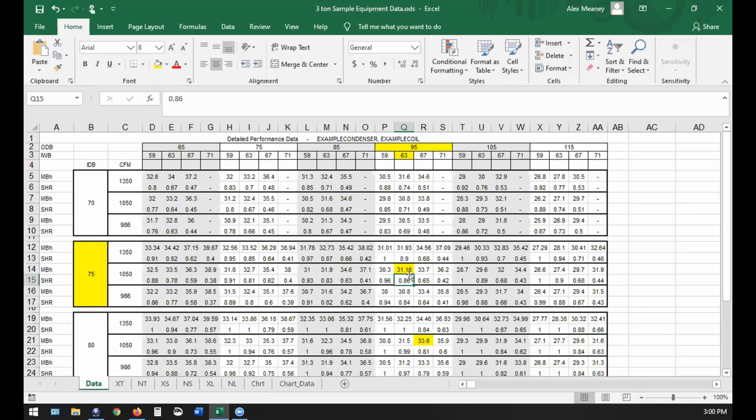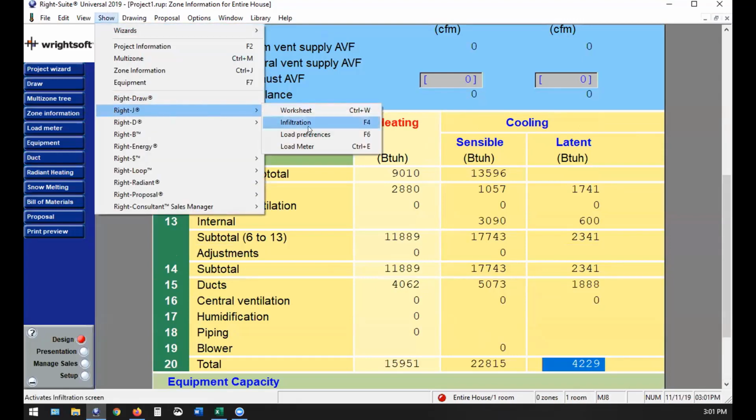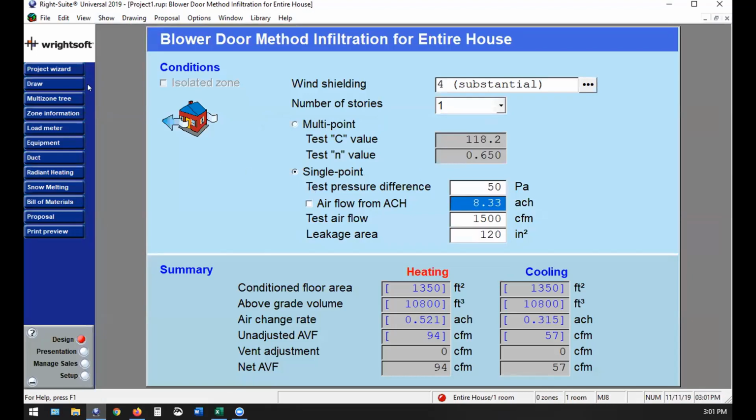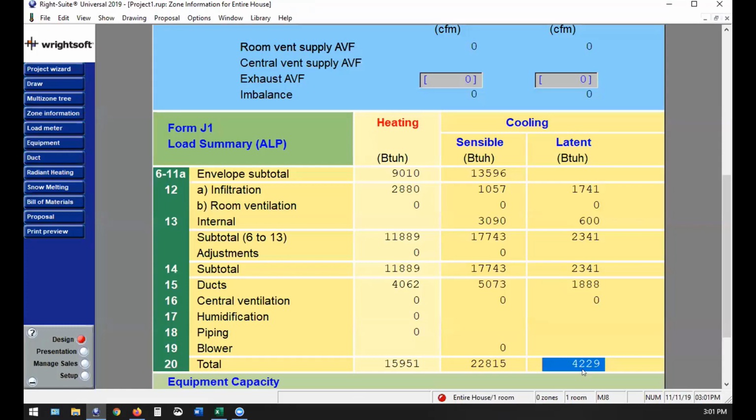And it's not as easy as how many tons it will be. It's a process of looking at the two. They gave us two numbers for cooling. We need to use them both, right? Because if I look at this system here, 42,200, and by the way, our number of air changes here was 8. So 8 air changes per hour here, nothing crazy like 12. Now this is in Orlando. This is 4,200 BTUs of latent control, roughly 23,000 BTUs of temperature control.